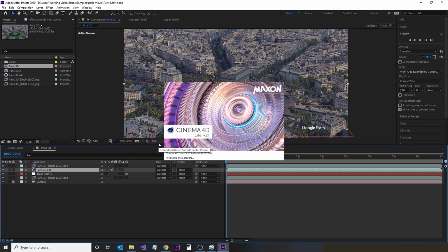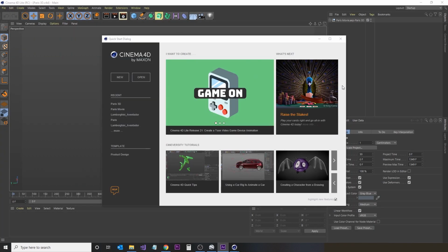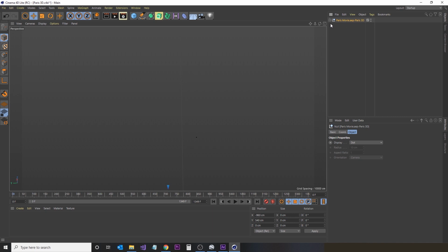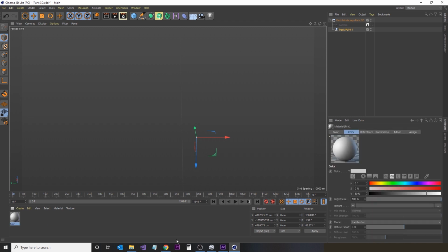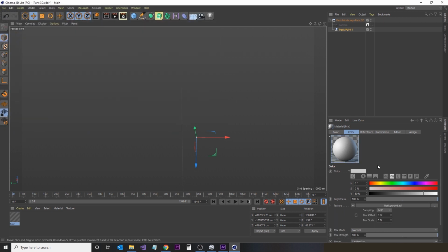So now it's going to launch Cinema 4D. If you don't have a registered version of the Cinema 4D Lite, it may prompt you for registration. You can do that and then come back to this point in the video. So you can see here it's got our project with our track point and our camera information. This can be fairly confusing, so let's bring it into the visual world. We're going to double click in the space in the bottom, which creates a new material. We're then going to click on the texture portion and select the video that we had just made.